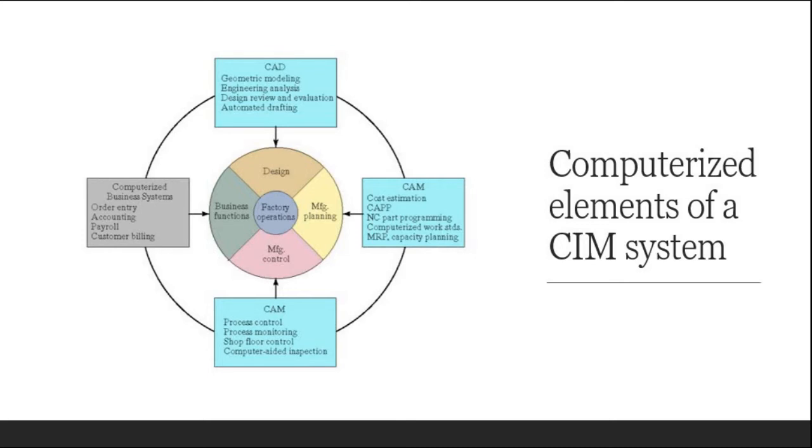The importance of CAM is also seen in computerized machinability data systems, in which computer programs have been written to recommend the appropriate cutting conditions to use for different materials. This is especially important when we are operating a metal cutting machine tool, in which the speeds and feeds should be determined for the machine for a given work part. Calculations are based on data obtained either in the factory or laboratory that relate tool life to cutting conditions.